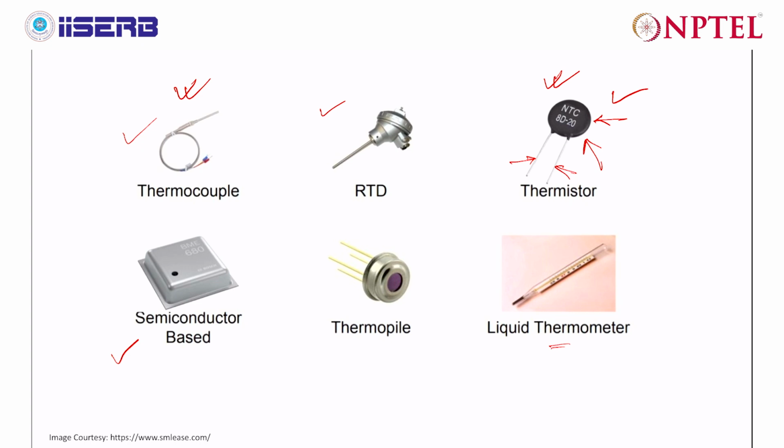We also have discussed in the classification, if it is an NTC thermistor, then the resistance will decrease with the increase in temperature, and if it is a PTC, then the resistance will increase with the increase in temperature. So both types are useful, and you will find the use of both these types of thermistors in various fields.